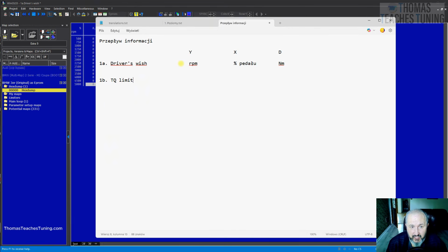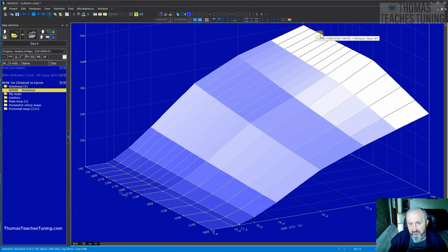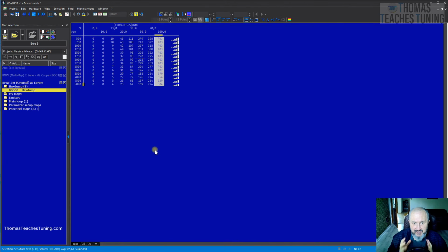Note that the maximum torque we aim to achieve in a system is set directly at the 100% position of the x-axis. So in the final column, there would be no need for a separate torque limit map if we properly set it. However, historically, the limit has been established and retained as a component of the driver system up to the present day, so we must live with it.